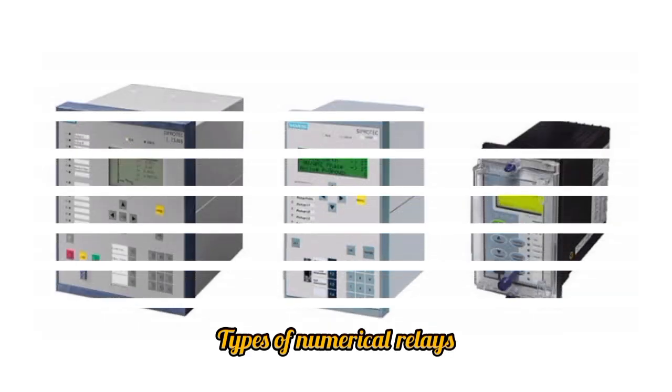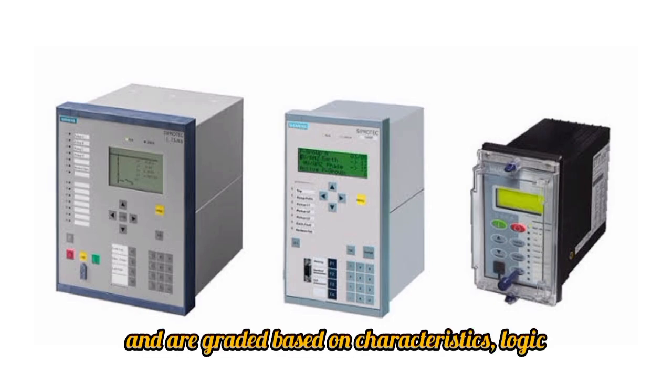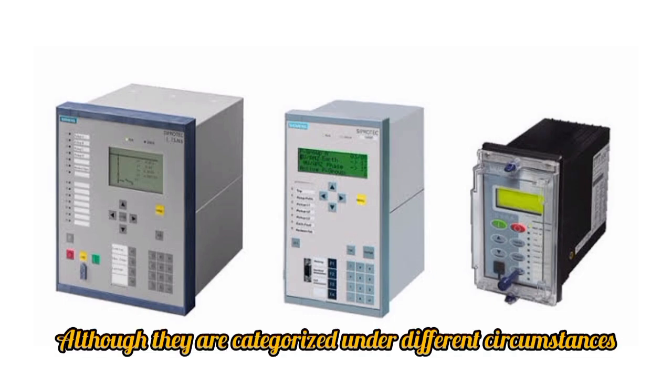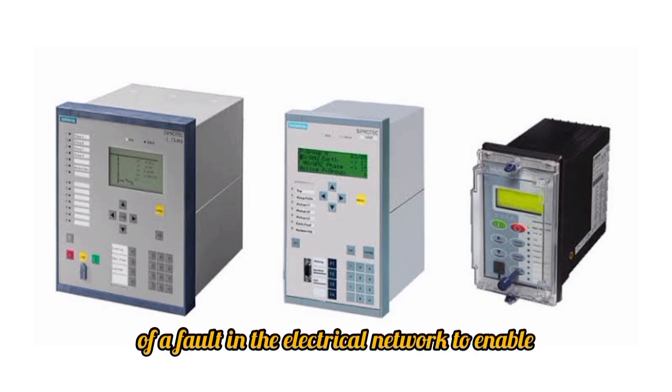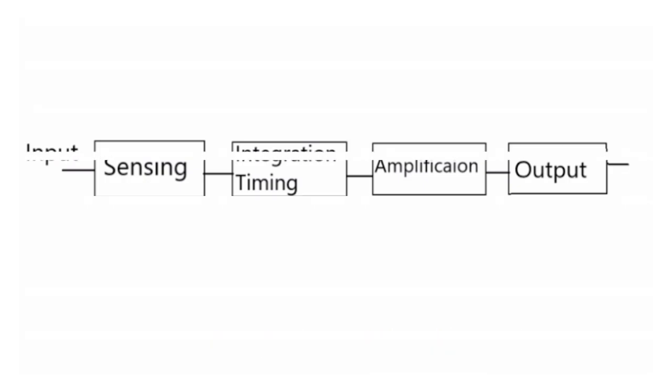Types of numerical relays. For different types of safety, numerical relays are used and are graded based on characteristics, logic, parameters of action and application. Although they are categorized under different circumstances, their function remains the same: to trip the system in the event of a fault in the electrical network. Based on logic. Such classifications are made based on the relay's logical operation.